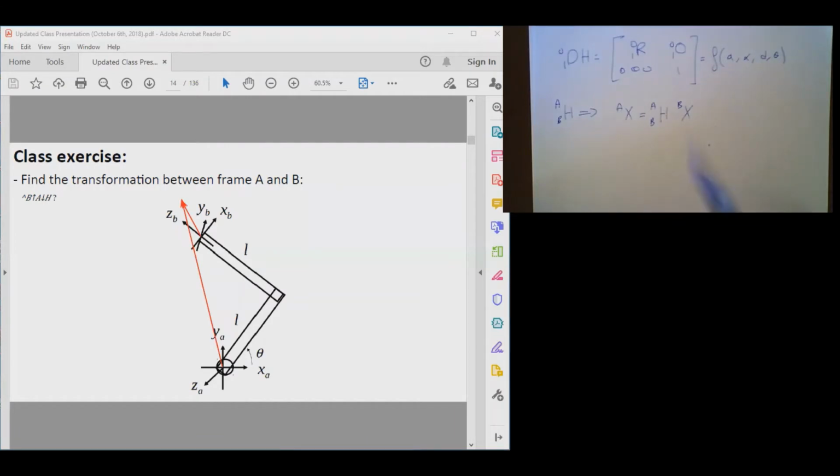When we program our homogeneous transformation, we always want to put a 1 here. But if I want to get only the actual rotational transformation, literally the projection of this vector onto XA, the projection onto YA, and the projection onto ZA, then I would put 0 at the bottom. That 0 will multiply the offset and kill it. Okay, that is it regarding that.